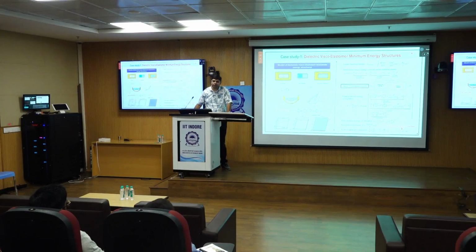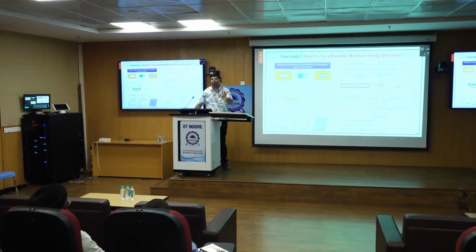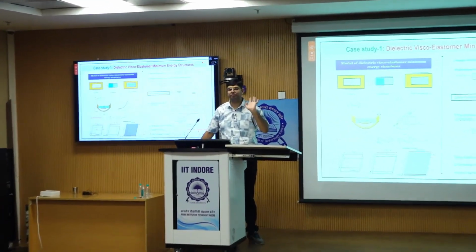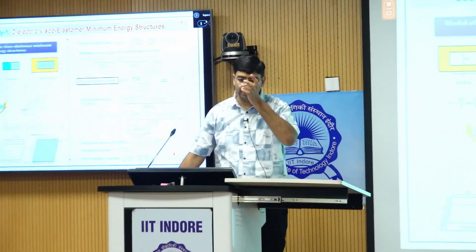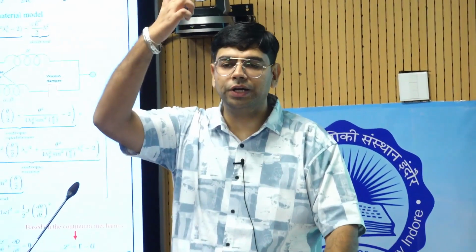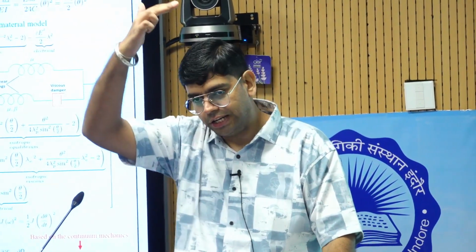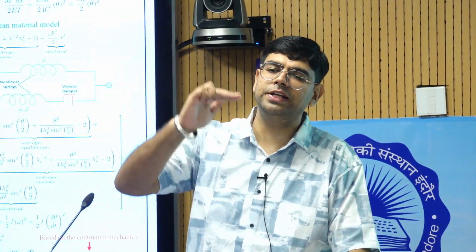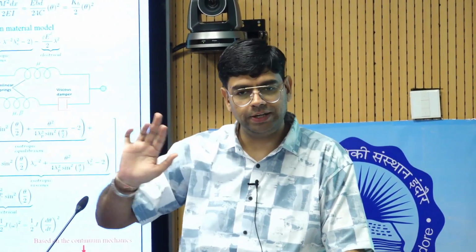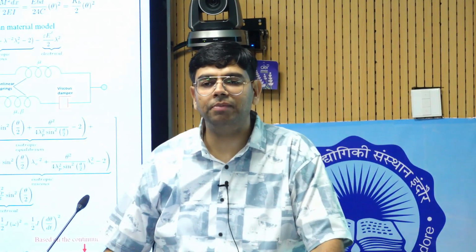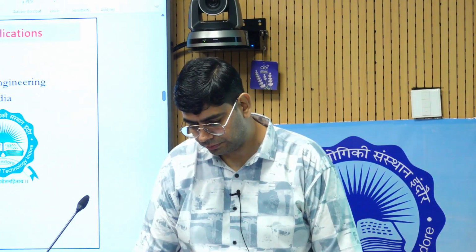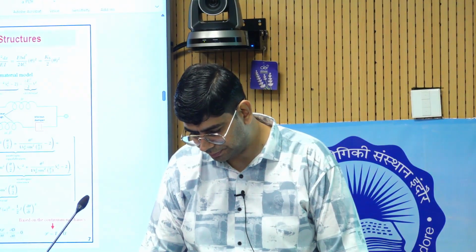Have you studied that whenever we are talking about the viscoelastic effect, two phenomena come: stress relaxation and creep. These two phenomena always come. So what is stress relaxation? At a particular interval of time, your stress will initially get degraded and reach a constant value. In creep, your strain will increase and then attain a constant value. Now when you are considering a Maxwell element model, I can show you that it will be very good. I have all these models with me.